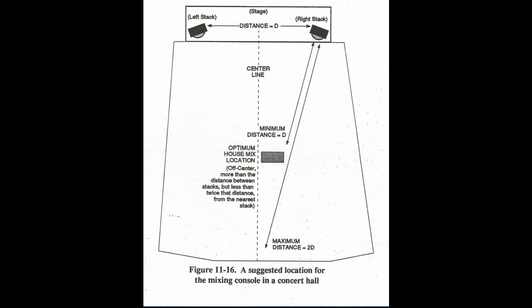An almost limitless number of factors, however, determine the acoustics of any given auditorium. The room's physical shape vitally affects the reflection of sound. If the walls are parallel, the sound will bounce back and forth between them, reducing the intelligibility of every word spoken.